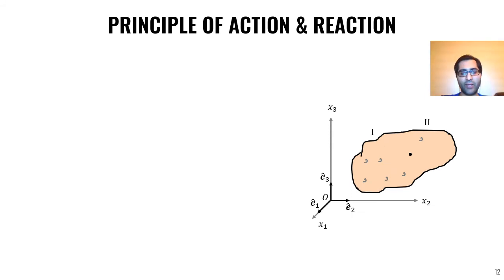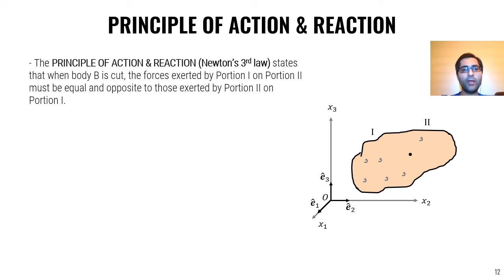The principle of action and reaction is something we often use when we work with traction or stress vectors. The principle of action and reaction, or Newton's third law, states that when the body is cut, the forces exerted by portion 1 on portion 2 and by portion 2 on portion 1 must be equal and opposite.